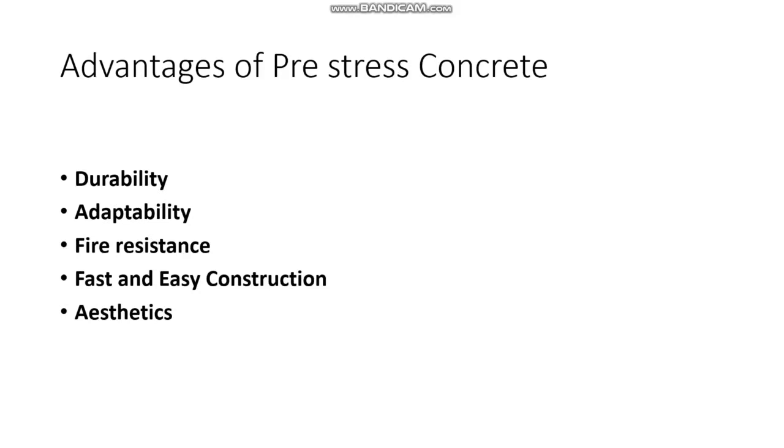The next important advantage is the aesthetics. Precast components can be delivered with a wide range of shapes and finishes, ranging from smooth, dense structural units to any number of architectural treatments. Strikingly rich and varied surface textures and treatments can be achieved by exposing color sands, aggregates, cements, and coloring agents using sandblasting and chemical retarders. Stone, tile, brick, and other materials can be cast into precast panels at the factory, enabling designers to achieve the expensive look of assembly.